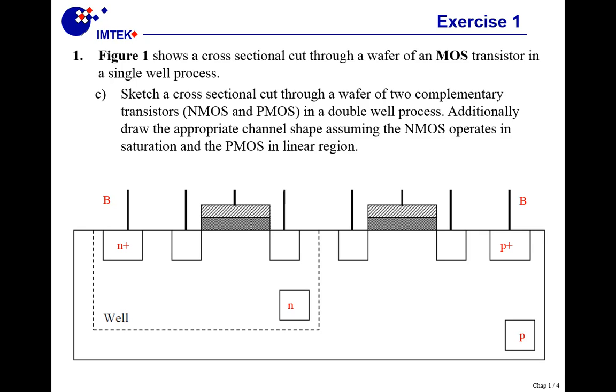The next thing we can continue with is determining where the gate, source, and drain are for both of the transistors. If we already know that this is a p-doped substrate, that means that the transistor on this side will be an NMOS. Therefore, I have to add an N plus doping in this terminal, and another N plus in this terminal. Since we have an N well here, then, analogous to the previous one, I put a P plus and P plus in this box.